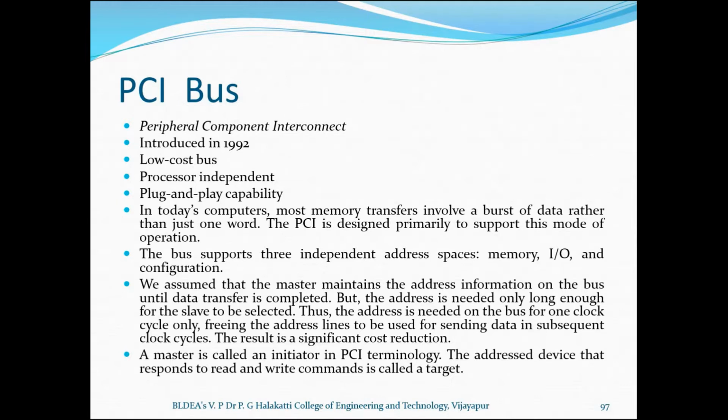To connect a new device, the user simply has to connect the device interface board to the bus. The software will take care of the operation, and PCI bus is defined for operations with either 5 volts or 3.3 volts power supply. Now, let us see how data transfer takes place using PCI bus.